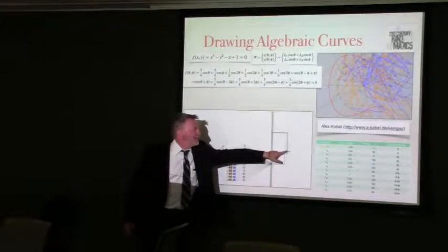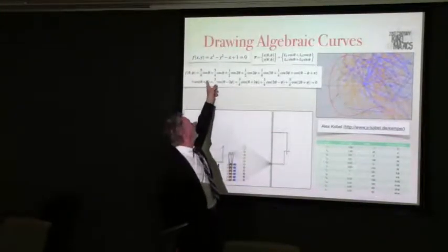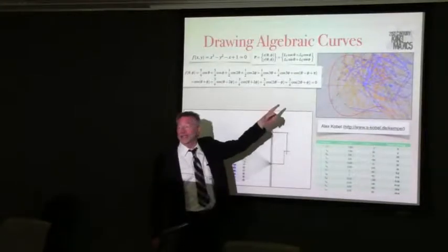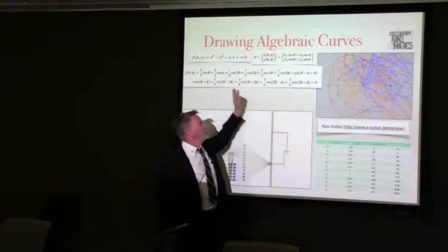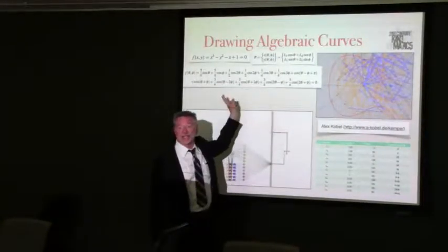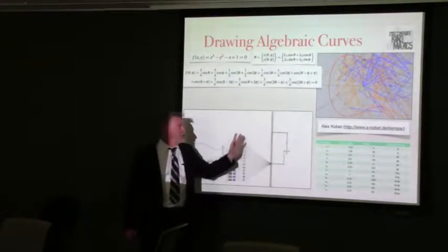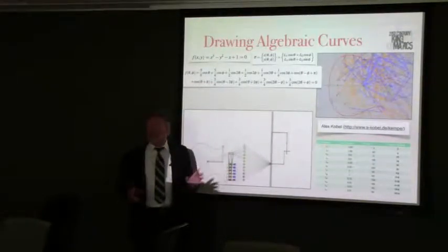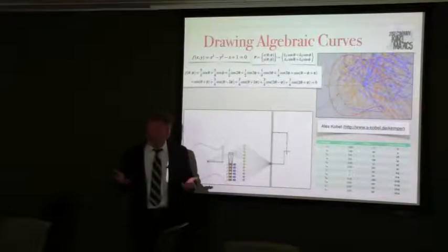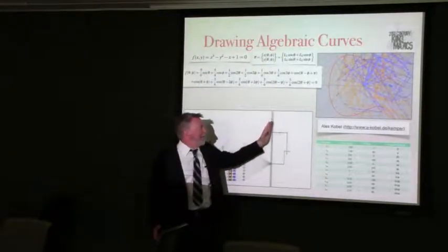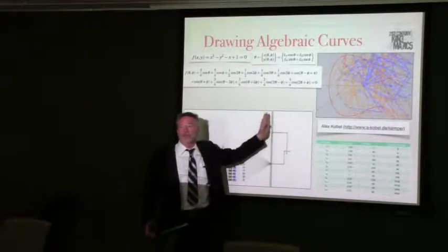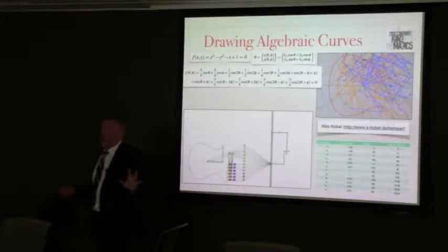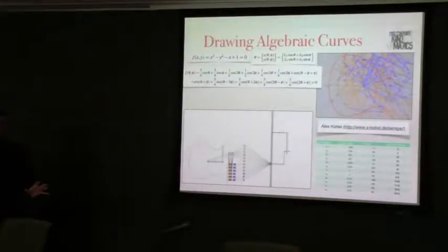This turns out to be the serial chain that you get when you write the algebraic equation out. You get what can be interpreted as the equation of a serial chain. To get the condition that it is an algebraic curve, you simply constrain the end of the serial chain so it moves on the x-axis and on the y-axis, and that's the entire essence of Kempe's proof.